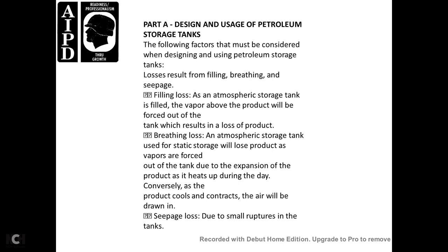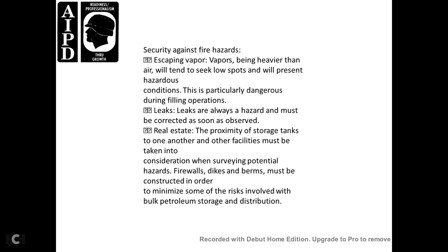Breathing loss: in an atmospheric storage tank in static storage, there is loss of product as vapor is forced out of the tank due to the expansion of the product as it heats up during the day. Conversely, as the product cools and contracts, air will be drawn in. Seepage is loss due to small ruptures in the tank.